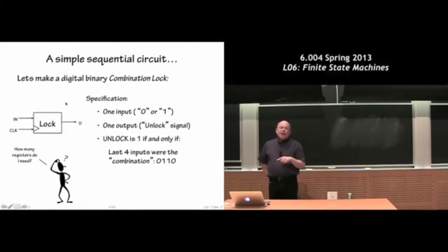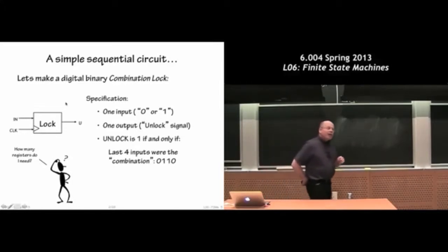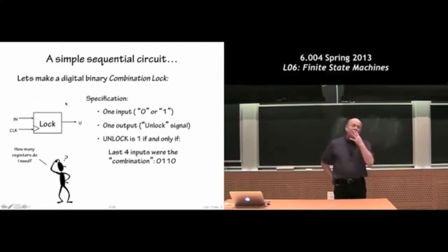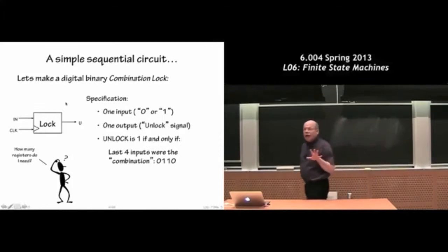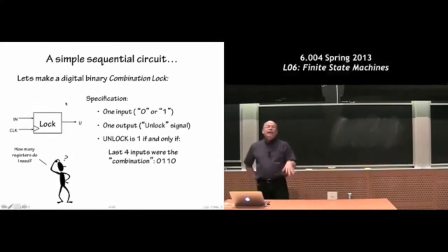And just so that we completely connect the dots here, this is a sequence of inputs we'd like our circuit to process. We can't do that with combinational logic, where the output is always a function of the current inputs. Since we want to process a sequence of inputs, we'll need sequential logic, and sequential logic always involves these state elements which get clocked. Everybody sort of happy with that? So that's the basic strategy. We're going to spend a moment now designing the inside of that circuit.